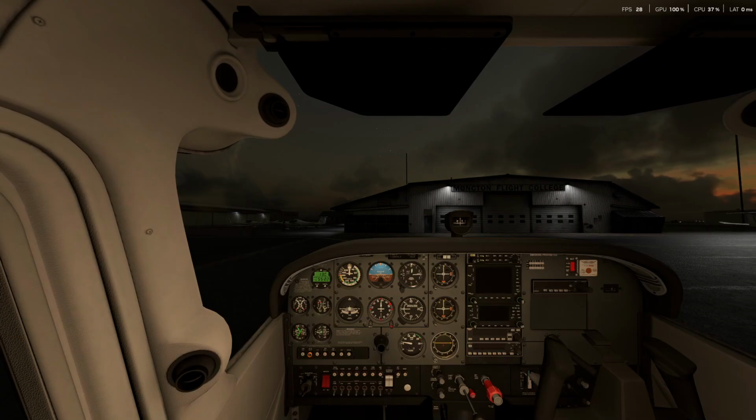Ignition switch. I can't simulate this in here, because when I do it, it actually turns off the propeller of the engine. But we'll just pretend that we're simulating that. Alright, so the ignition switch off and then both. That check is to make sure that there are no live mags. Alright, so throttle back up to 1,000 RPM and make sure idle cut off.